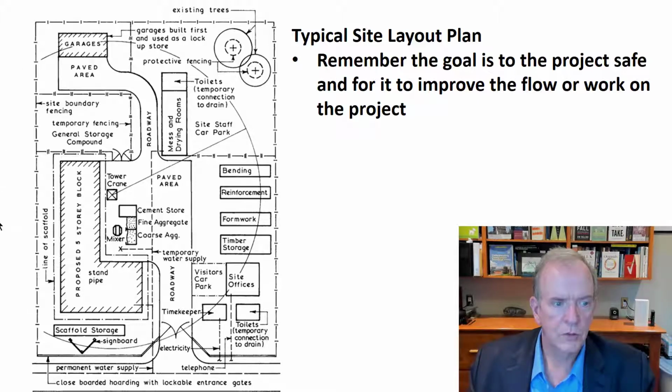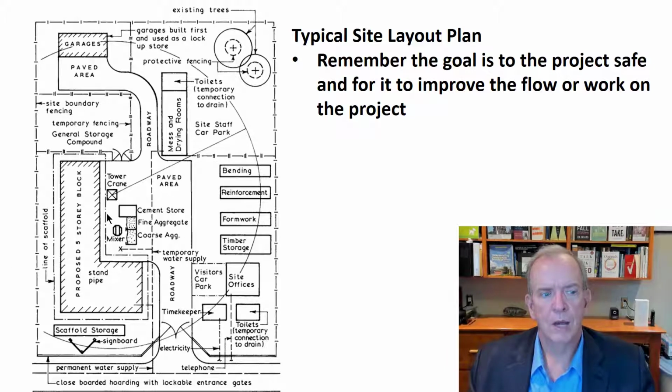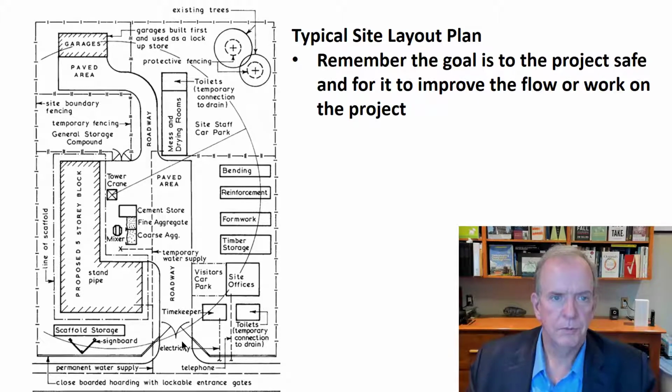And then you're also looking at, okay, so it's going over the neighboring property, so we better get special permission. You can't lock a tower crane, so if there are high winds, it has to be able to move directionally. So you can't say, okay, I'll lock it, it'll never go over that property. It will. So that was the permissions aspect of it, and if you can't get that, then you might look at a luffer crane instead.